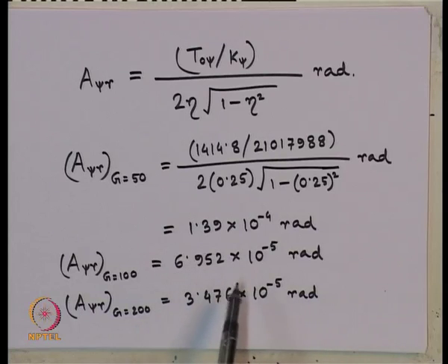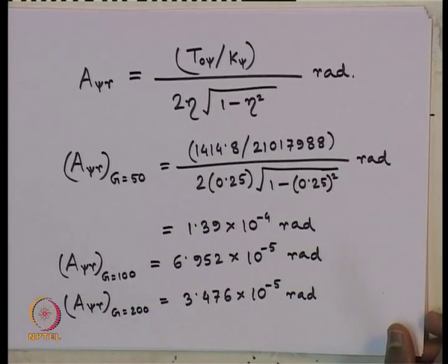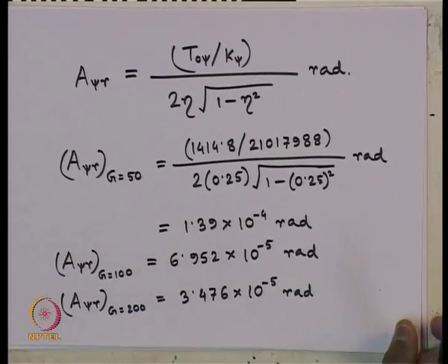You can check whether the calculated values for resonance condition are bigger than at operating frequency or not. If not, then probably we have made some calculation mistake somewhere. So, for a design or a design check, this way we have to carry out the calculations. This completes the rocking mode of vibration case.